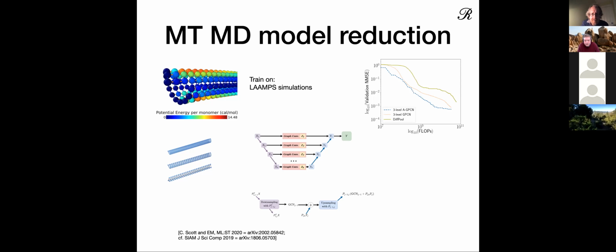And so there's 4 or 5 coupling constants, and it's all run in the LAMMPS molecular dynamics simulation. And this is not a very well understood art, because there isn't a deep literature the way there is on atomistic simulations on what these potentials ought to be. So we pick one that at an unreasonably low temperature does not make the microtubule explode when you pull on it. And so just to get the quote ground truth, Corey had to do some parameter optimization to get a reasonable straw man. But presumably, as we know more, we'll be able to get those potentials better.